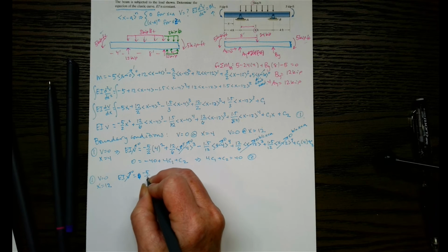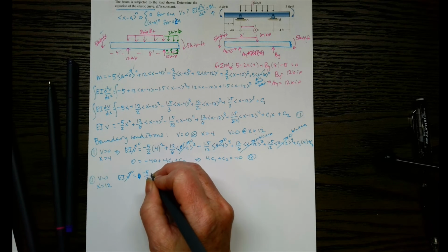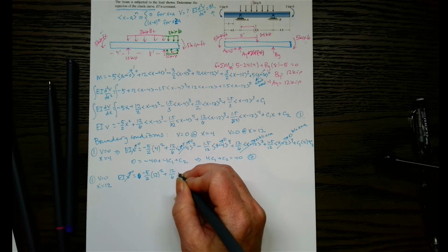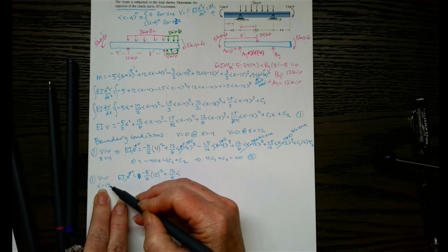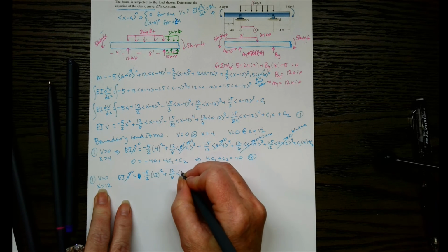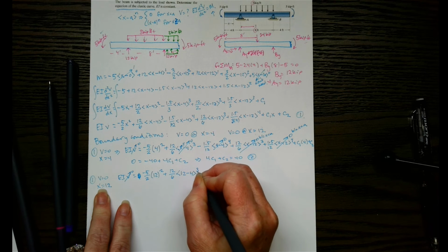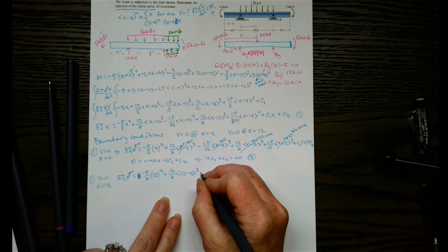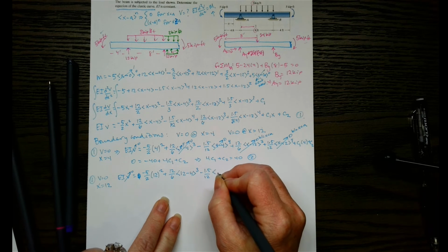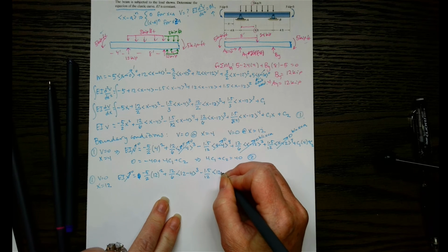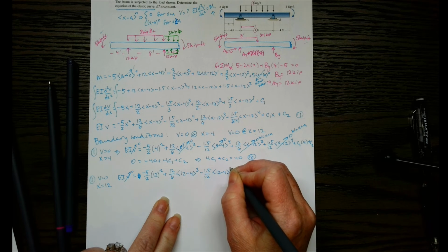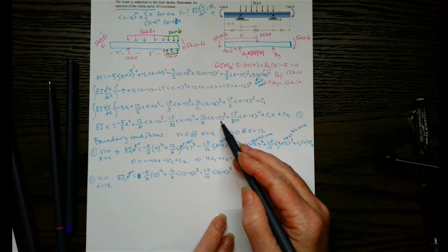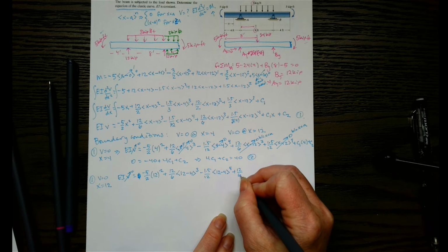Now the right side, we've got negative 5 over 2. Then we just have X squared, so it'll just be 12 squared. Plus 12 over 6. X is 12, which is obviously greater than A, which is 4, so we just plug in 12 here. So 12 minus 4 cubed. Then we're at this one, so negative 1.5 over 12. Again, we've got X minus 4, and 12 is greater than 4, so we just plug in X equals 12 and raise that to the power of 4. And then now we're over here. Plus 12 over 6.